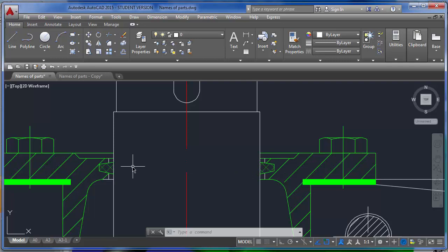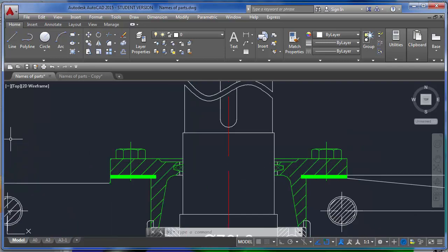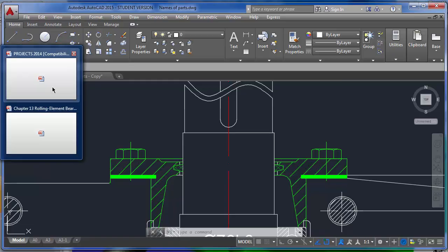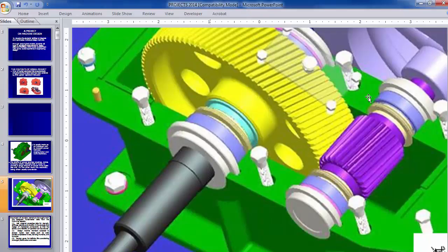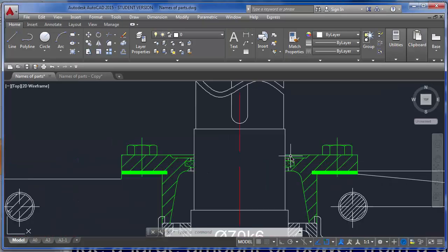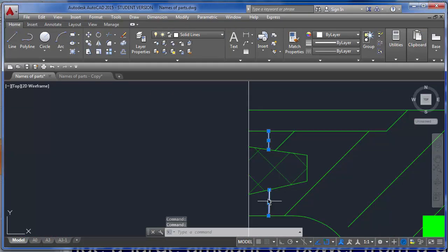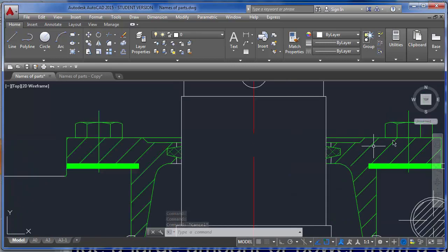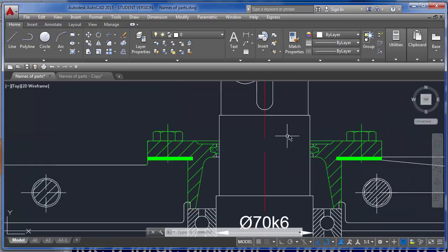This is a ring around the shaft, and what it does, it prevents oil from going out, and it's inside this bearing cover. And where it is in real life, inside this bearing cover, or inside this bearing cover, or if we go here, it's inside here, somewhere else here, because oil might go out of this hole. Okay, and you see there are two lines here, one line, two lines. These are clearance, because if there's no clearance between this thingy and this guy, it will get stuck and it will not be able to move.